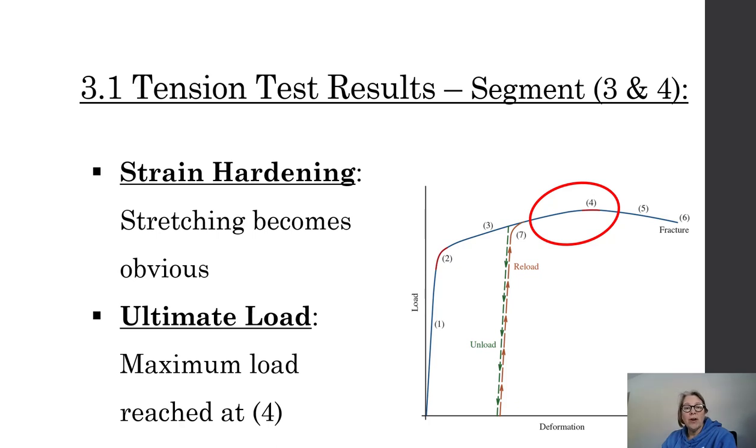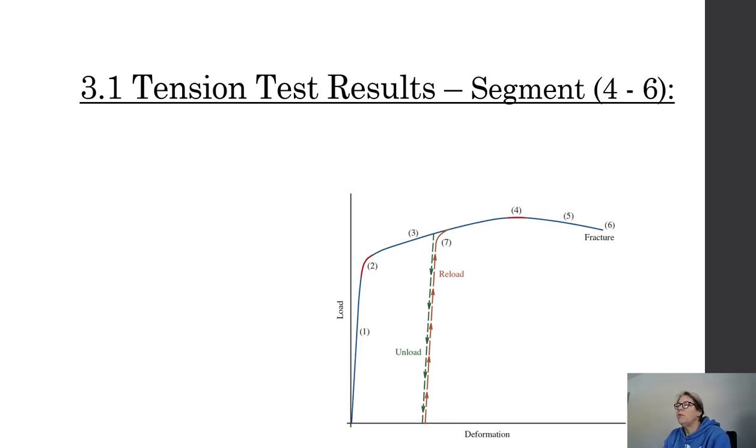So when we say stress ultimate, okay, stress U, that's the ultimate stress that we can handle. Okay, it's above yielding. It's in the plastic area. And it is the ultimate stress we can handle. And we hit that, and then whoop, usually you can just see the load almost going away and fracture occurs. So then we have a stress at fracture, which is beyond and lower than that ultimate.